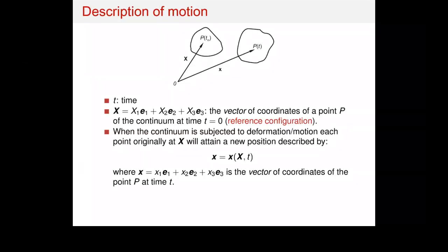All right, I'm going to discuss the strains. Now, in principle, the strain and the stress are not very different. I mean, talking mathematics, the strain tensor and the stress tensor are pretty much the same. So the good thing is everything you have learned about the stress tensor would apply pretty much exactly the same way to the strain tensor. The strain tensor itself is not different. It's just how you derive it and the physical meaning of that.